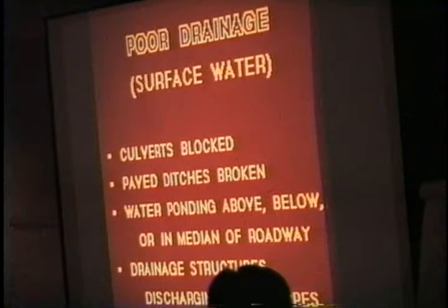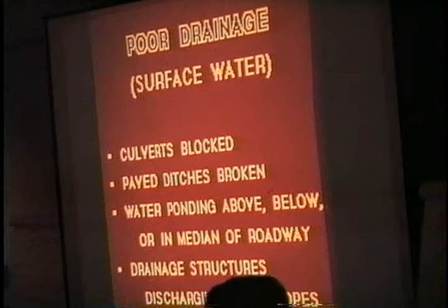And when it gets to the end of the bridge, you may have a lot more water and have to get rid of it quickly. What we recommend is don't put those side chutes right by the end of the bridge, because that's a surefire way of having a lot of erosion and instability.